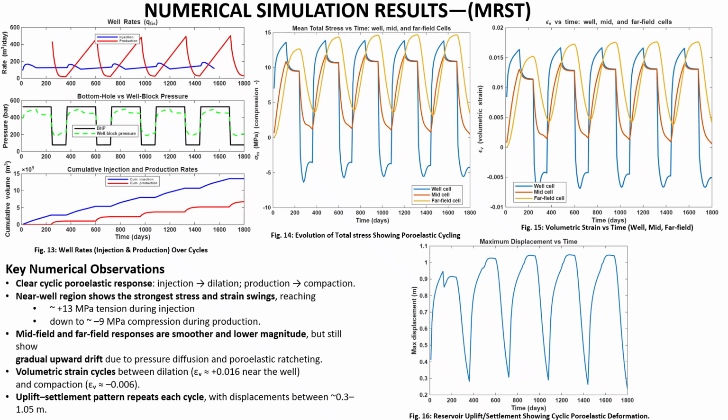So next I will show how pore pressure cycling shifts stress states on a Mohr diagram, and we will see the failure criteria which we are going to use to assess these results. On this slide, I'm using the Mohr circle to examine shear and tensile failure risk at key stages of the injection, shut-in, and production cycle.